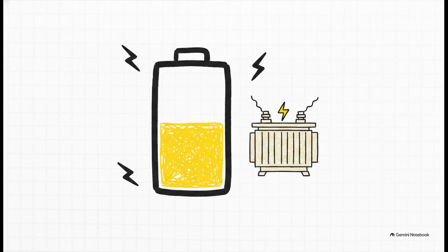Because those copper losses are constantly fluctuating, like how power demand spikes in the evening and drops at midnight, we need a clean mathematical way to represent how much work the transformer is doing at any given moment. Enter our variable, x. We use x to represent the fraction of the full load. So if your transformer is running at exactly half of its rated capacity, x is just 0.5. This simple little variable is literally the key to unlocking our maximum efficiency condition.